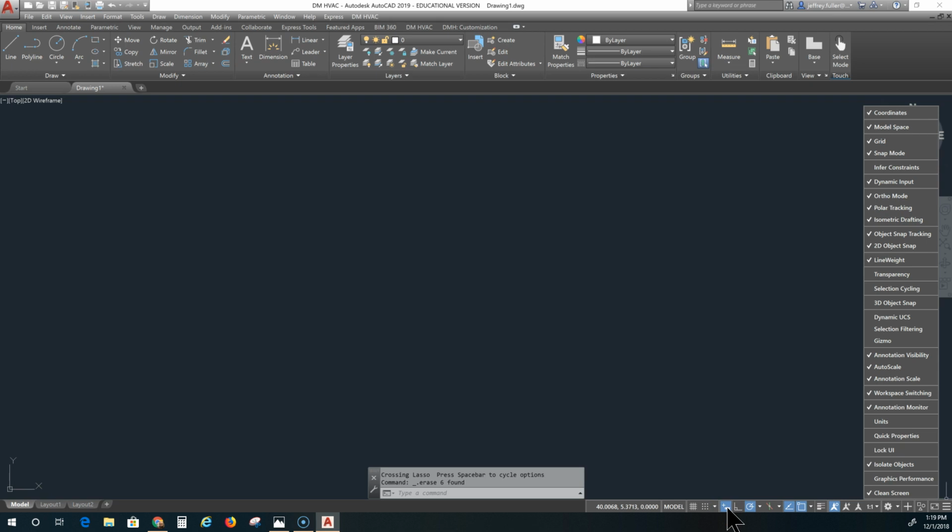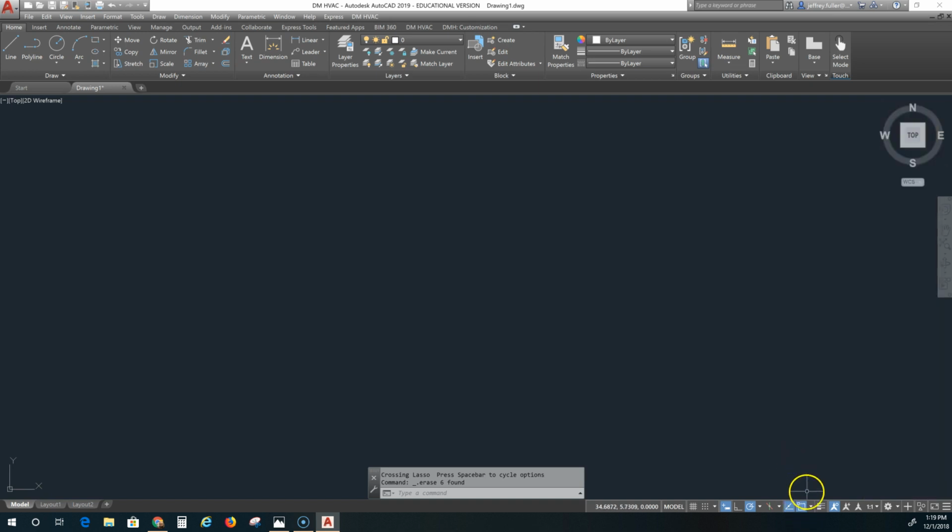Okay, a couple of other features that we need to make sure that we have on our status bar and that they are turned on is this one right here. It's a square with a smaller square up in the upper left-hand corner, and that is snap cursor to a two-dimensional reference point. And I'll show you how that works in just a moment. And you also want to have this one on. It says show snapping reference lines. Okay, and those are two ways in which you can help guide creating your geometry.